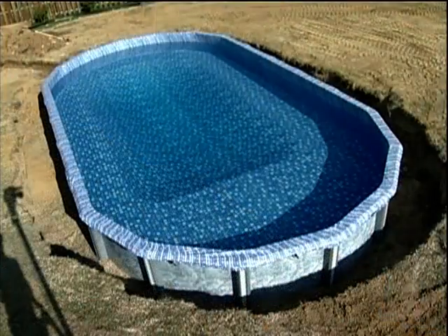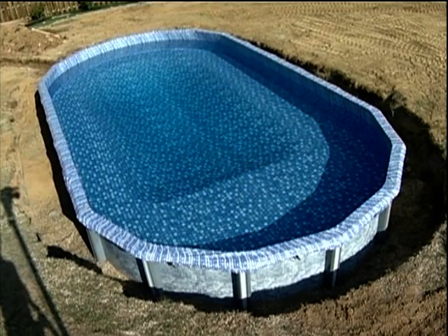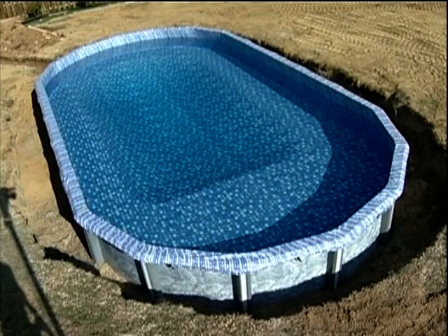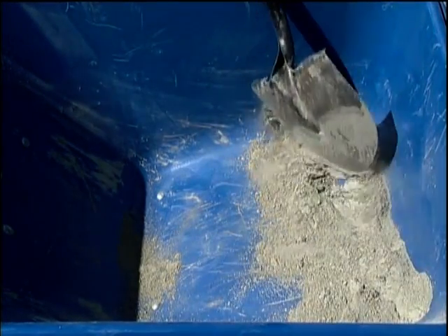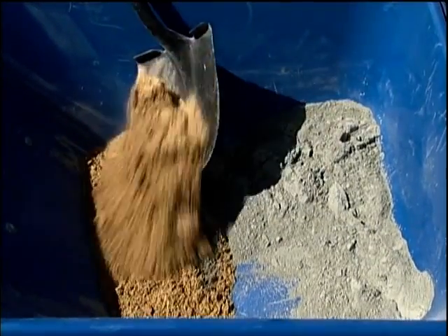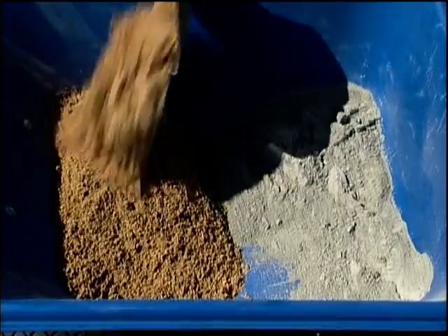The purpose of the slurry is to make a form around the pool which will be used to hold back the soil. Also, the slurry allows the liner to be changed without the soil collapsing the pool wall. For the slurry composition, use 1.5 95-pound bags of Portland to 1 ton of sand, or 142.5 pounds of cement to 2,000 pounds of sand. This mix is rated at 365 psi.